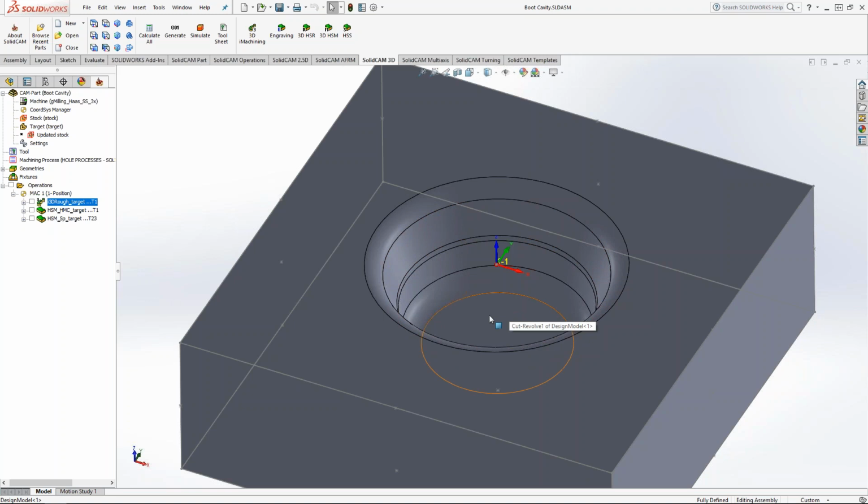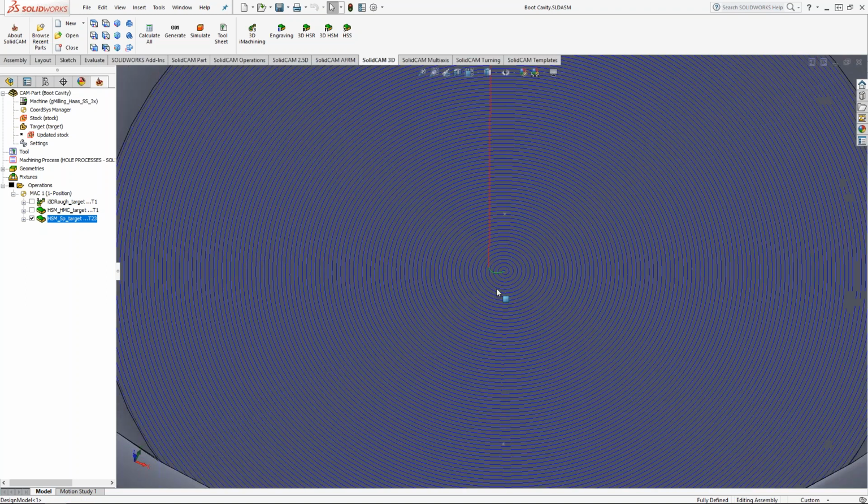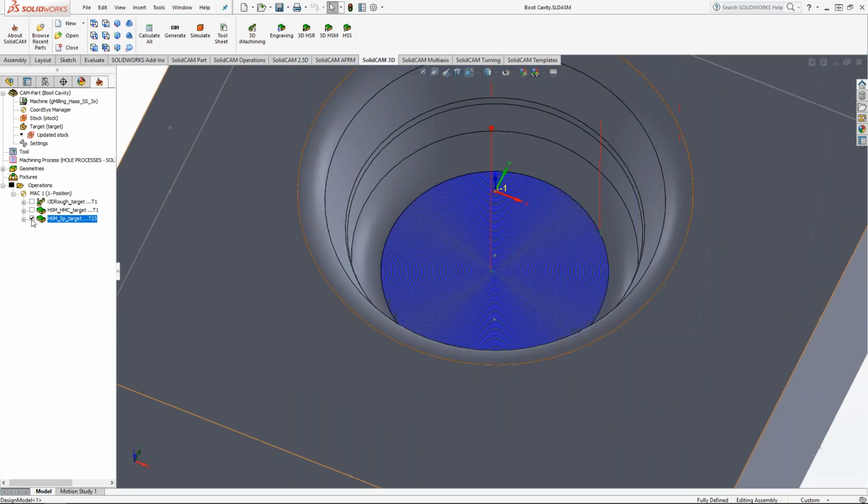Now on the bottom, I would use a ball nose just because I didn't want that swirl that you get with a bull nose or a flat nose end mill on a flat surface. That's why I actually used this half-inch ball to do this toolpath on the bottom. Okay, makes it easier to polish out.